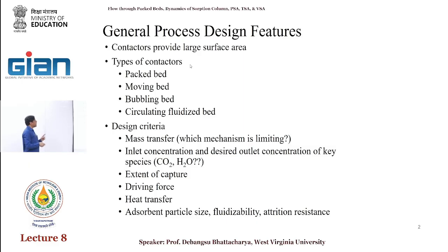So particle attrition resistance is an important thing. But if you have a particle that does not have very good attrition resistance, then you can use it in a moving bed. The moving bed is a good compromise between the fixed bed and the fluidized bed, right? It is a much more packed bed, and the entire bed moves through the system. The particles do not collide with each other as much as in a fluidized bed. So all of those things are important to consider.